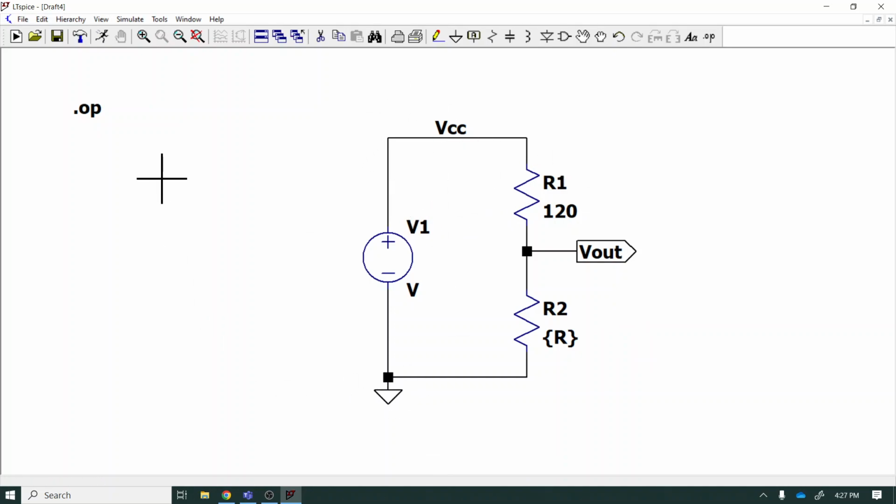describes all the connections, and then has a series of commands for what you want to do. Now, they've kind of graphicalized all of this part, but the actual running of the simulation, they've not really created a graphical version of that. Within LTSpice, you actually put the text directives in, and it shows them on here. So .op means run a